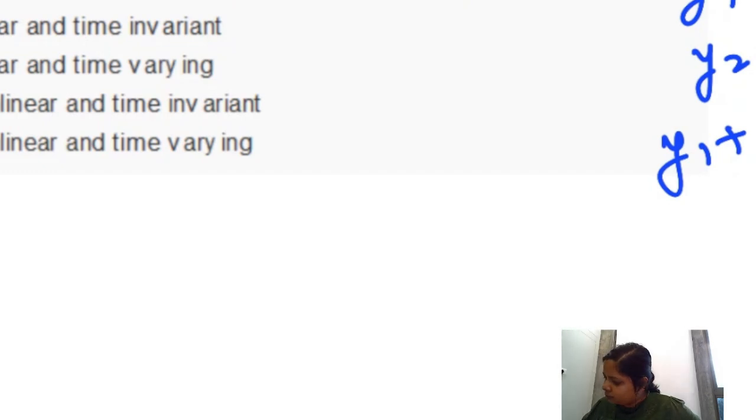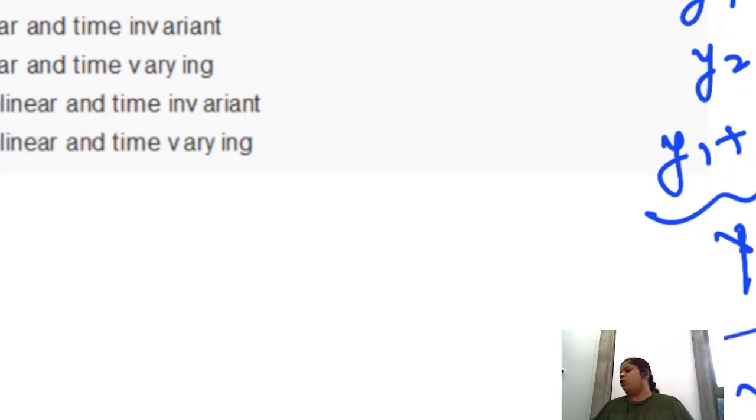So if this were a new signal y, this is a new signal u. So basically you again get this only for a combination of signals also. So it is a linear system. Now why is it a time varying system? Because you have t explicitly here. If t is equal to 0, yt would be 0. If t is equal to 1, yt would be ut. If t is equal to 2, yt would be 2 ut. So as time varies, your output is also varying.